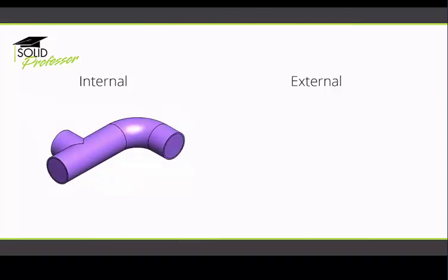As I mentioned in the introduction to this course, SOLIDWORKS Flow Simulation is capable of performing both internal and external fluid flow analyses. However, prior to running the analysis, you might have to do a bit of setup work to prepare your model for the study. By internal flow, I mean that the flow is bounded by solid surfaces on the outside, such as flow through a pipe or duct. A good way to think about this is that the fluid enters a closed system through one or more inlets and exits the system through one or more outlets, with the exception of some natural convection problems that have no openings. For internal flows, there are two aspects of model preparation that may be required in SOLIDWORKS Flow Simulation. They are creating lids and checking geometry.